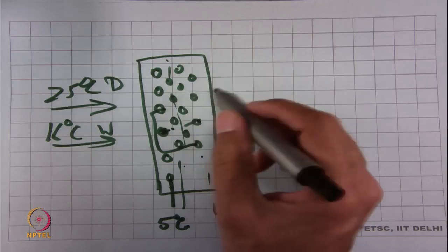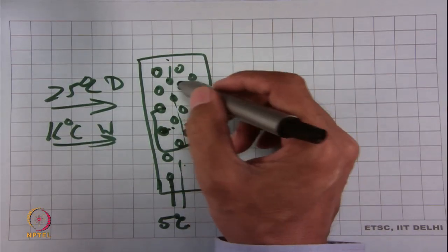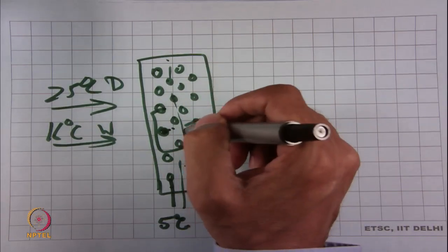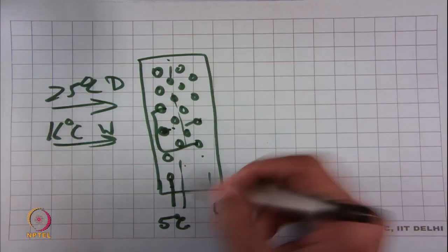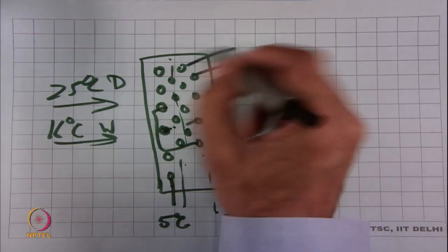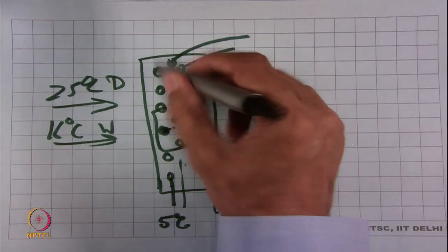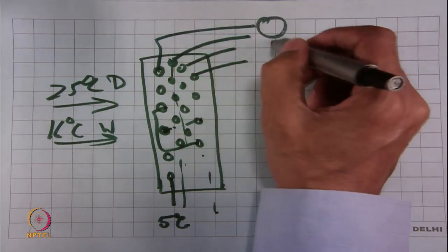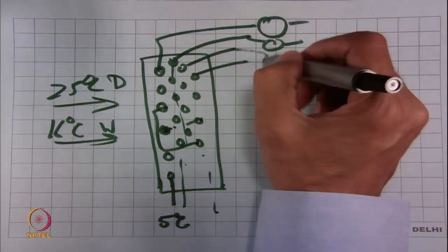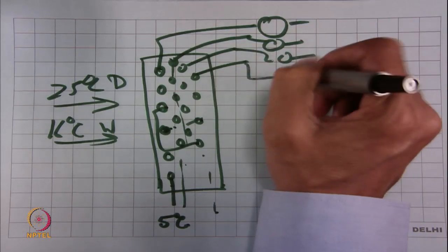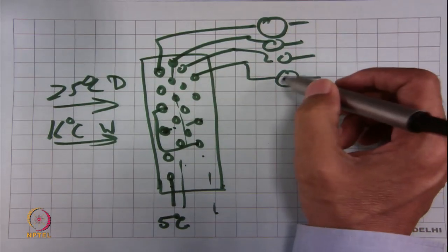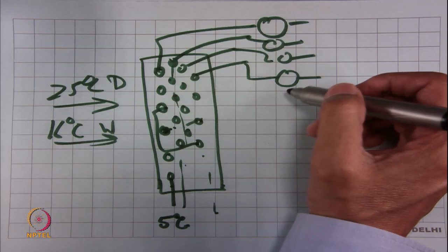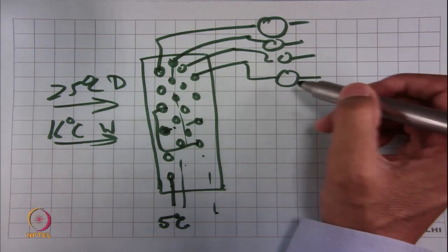So we could envisage that there is going to be a difference, and then the 2 inside circuits, again midway in the coil design we swapped them, and then there were 4 outlets available from each of these circuits. So we put a side glass in each of these circuits. A side glass essentially allows refrigerant to enter that device, then there is a glass opening and there is an indicator for moisture.